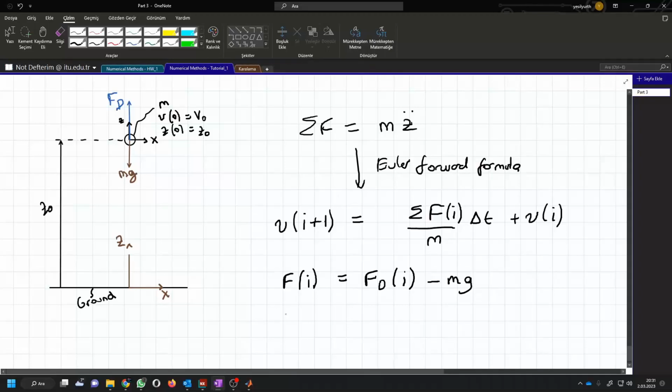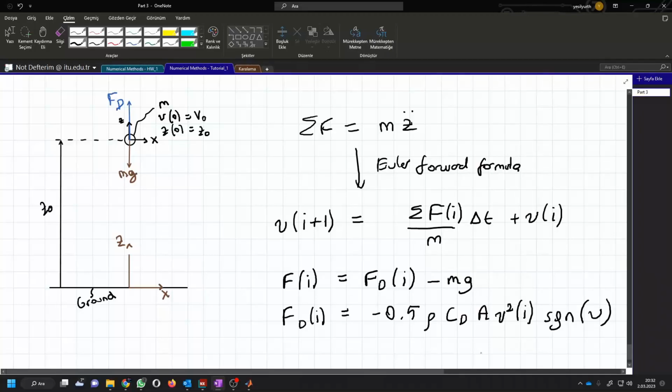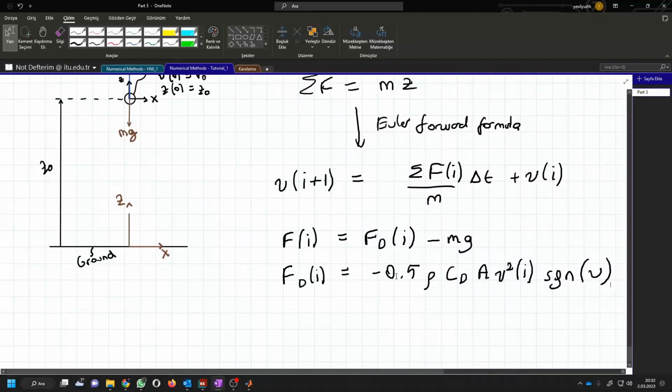So what was my Fd? It was minus 0.5 times rho times Cd times A times square of Vi times signum V. We have to remember this because of our sign convention.